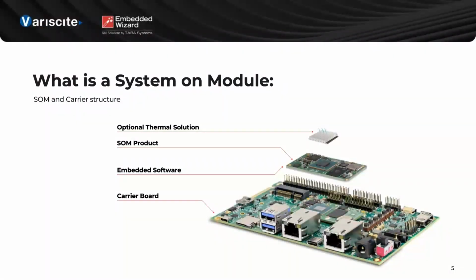So when you start with the SOM, you can customize it according to your needs in terms of components, like the quantity of RAM, the size of the eMMC, and whether or not to have Wi-Fi, Bluetooth, or other components on top of it, like the CAN controller for those specific SOMs, or the touch controller for others. Being fully customizable, the customer has several degrees of freedom in order to get the product that better matches the target.